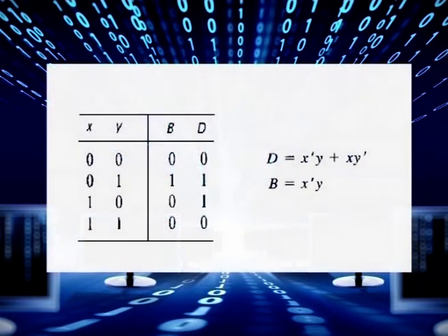Let us see the truth table and we can easily notice that the only case where we need to borrow 1 is when we subtract 1 from 0. It is interesting to note that the logic for D is exactly the same as for S in the half adder.